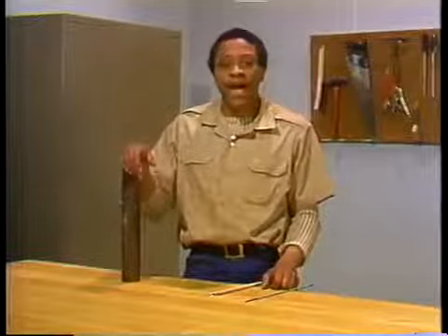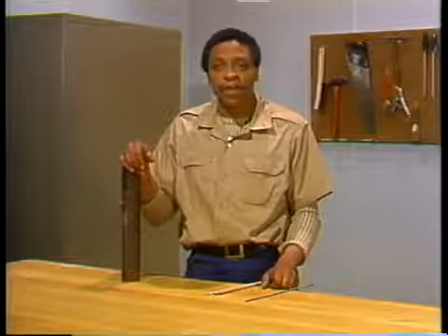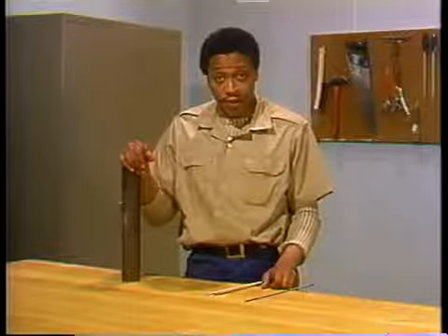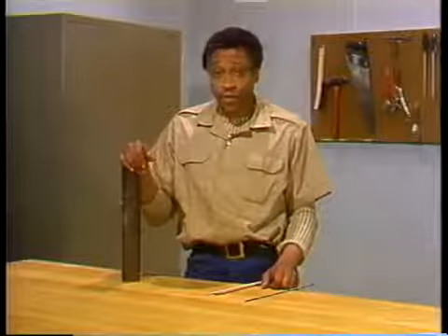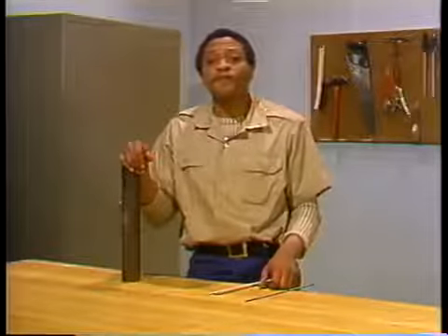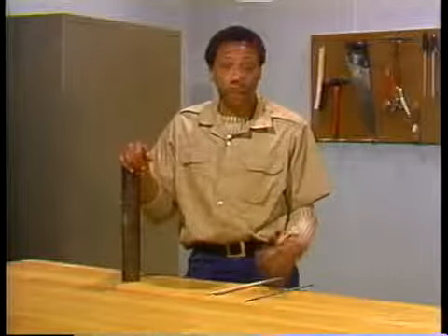The first method of tube repair is the replacement of a section of tube. Here, the length of tube containing a failure is cut out completely and replaced by a new section of tube. Replacement of an entire tube section can be done to repair any kind of tube failure. Replaced tubes are as good as new ones. You can replace every tube in the boiler or as much of one tube as necessary.